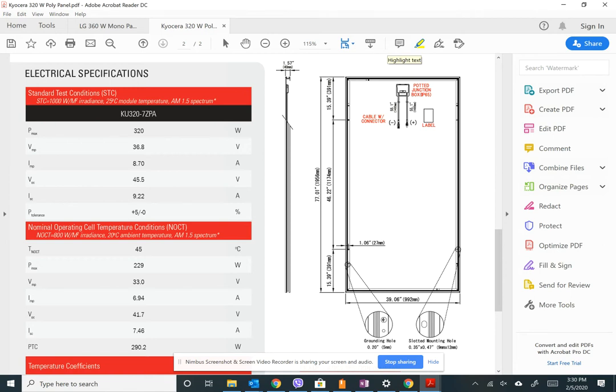And I said on Monday that is more of a realistic operating condition. But we are looking for the worst case. So that means that we'd probably not use NOCT. We would want to use STC. Because notice also that your VOC for NOCT right there is less than your VOC at STC conditions. Okay, so we're going to use the STC one. So 45.5.